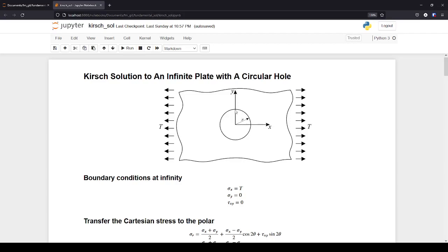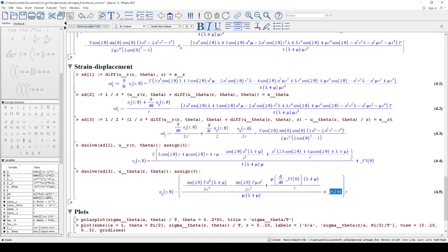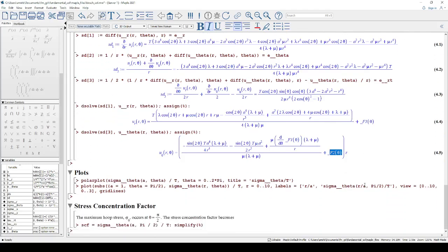And here you may say that y may move down from this point, but x does not change. So you may use this point and this point for y being constant, and here for x being constant, and use this initial condition to solve for the displacement for this kind of problem. So it depends on what kind of problem you assume to solve.